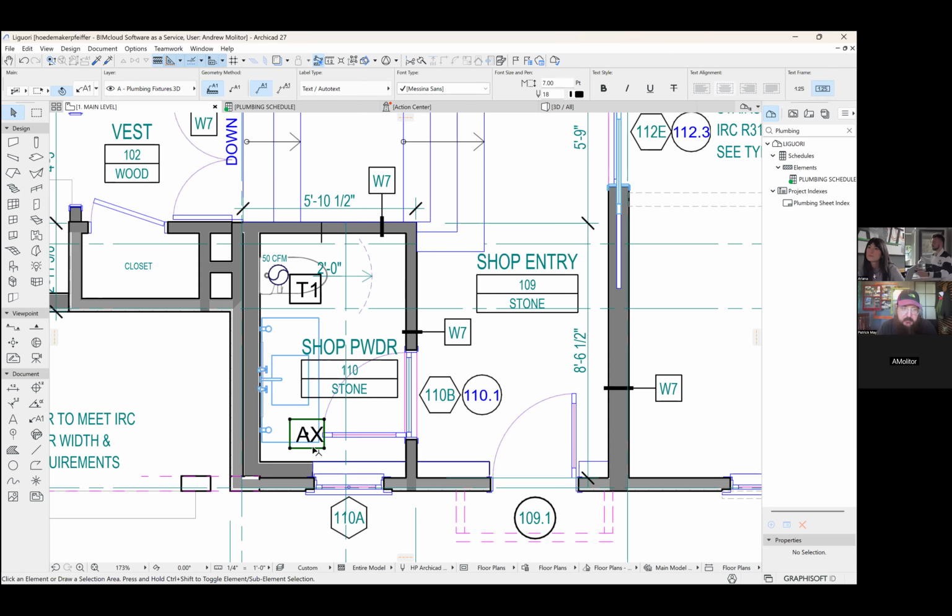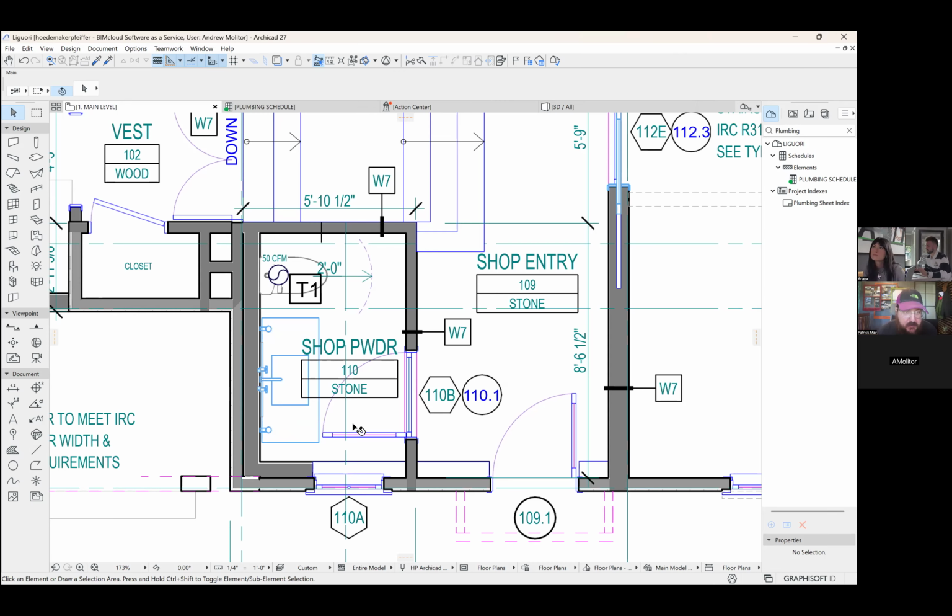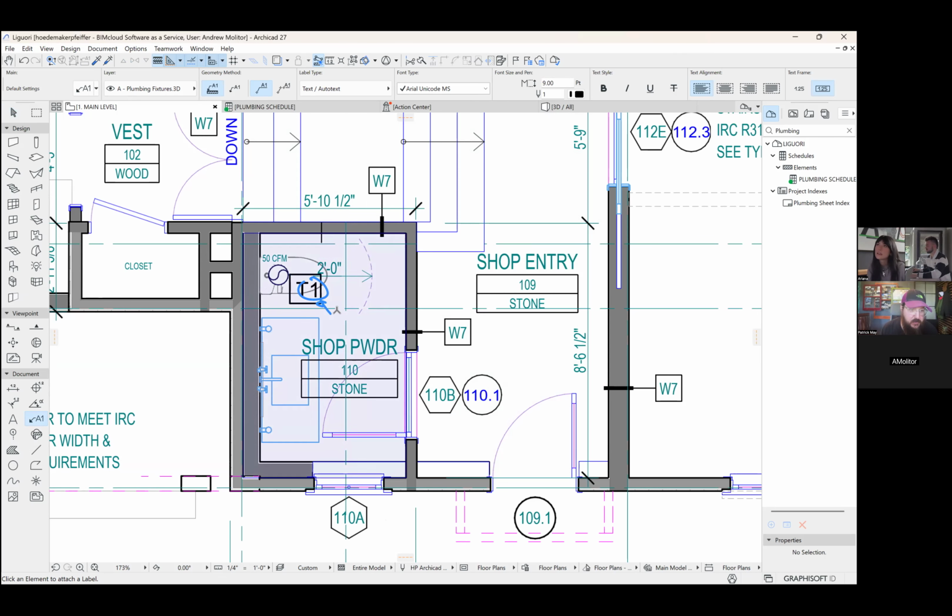Thank you. Another really cool trick is if I want to grab the settings of this and just start clicking on things to associate other labels. If you hold down the, I believe it's the Alt key, you're going to see your cursor look like a little eyedropper. And if you eyedrop the center of this label, make sure it highlights the label, and click. Now it activates the label tool and makes that label's default settings the standard. So now when you go to click on another element to tag it, for example, it's going to use that same label type.